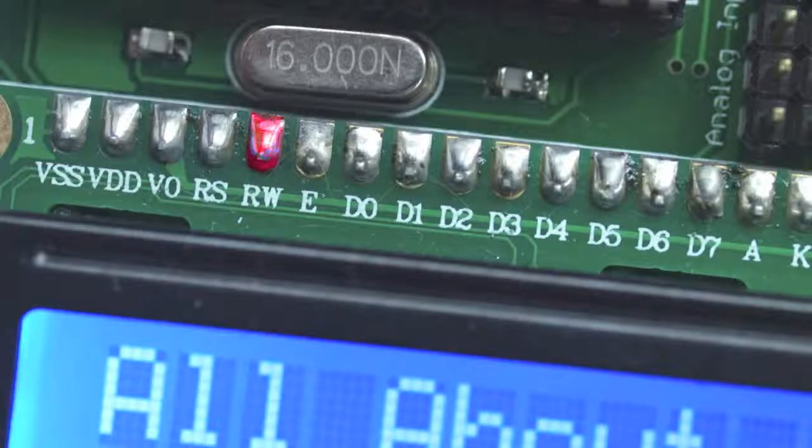The first thing I might want to do is clear the display. The binary code for this command is 00000001. If you remember, to send a command the RS pin must be low, and to write to the LCD the RW pin has to be low as well. Then I would make the parallel data port on the LCD equal the binary code I want to send.